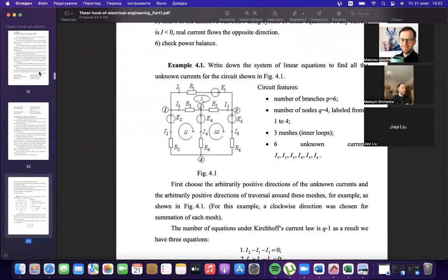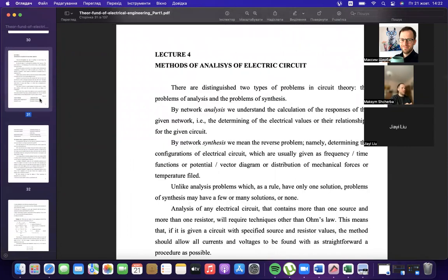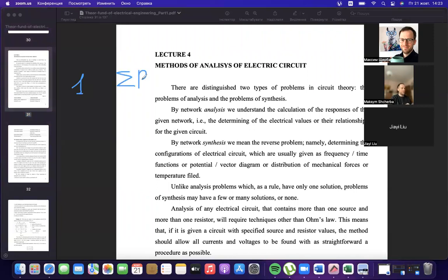We discussed that generally we have two types of circuits. If in a circuit in our mathematical model we have only one source of energy, then it is called simple, and we could calculate the equivalent resistance of such a circuit, and the current near the generator will be the value of the generator divided by the total resistance.